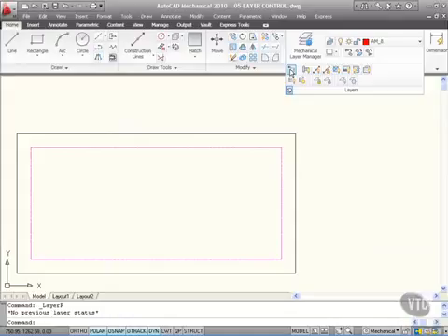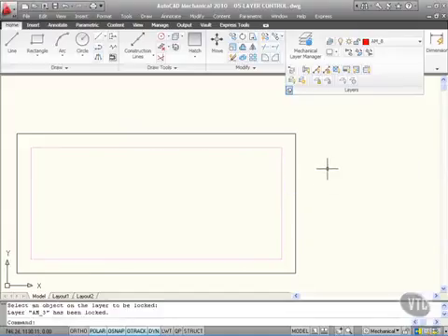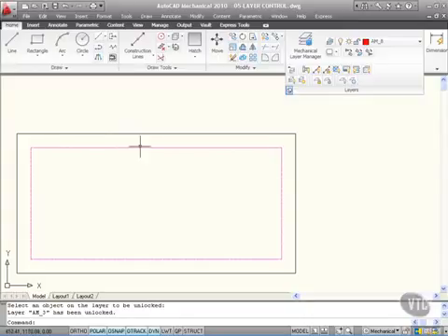So if I keep clicking that, does anything happen? No, it doesn't, because I haven't changed any layer settings. I can also unlock the layer of a locked object layer very quickly, and I can also lock. So if I lock now and select the object on the layer to be locked, if I click on one of those there like that, you'll see they sort of fade a little bit. That's the layer settings. They're now locked. If I want to unlock them, I can quickly go here. Notice the little lock symbol, but as soon as I click, they become a bright color again and they're unlocked.